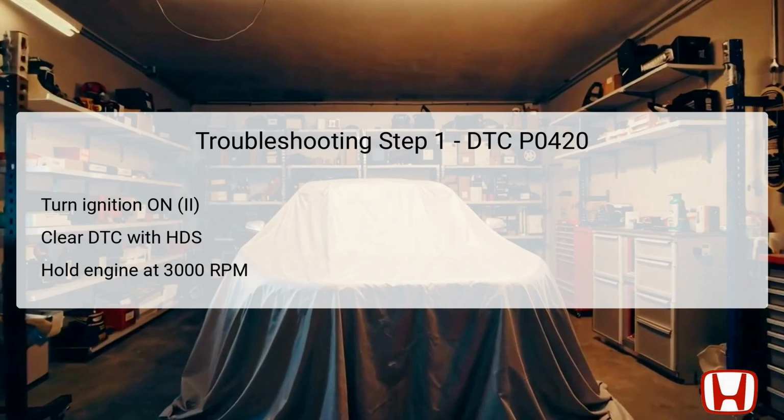In the first troubleshooting step for DTC P0420, it's essential to start by turning the ignition switch to the on position without starting the engine. Following this, use the Honda Diagnostics System, HDS, to clear any existing diagnostic trouble codes. This step resets the vehicle's onboard systems and prepares it for a fresh diagnostic assessment.